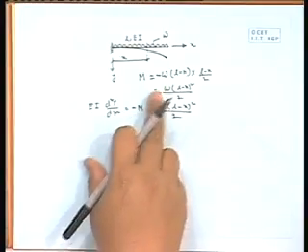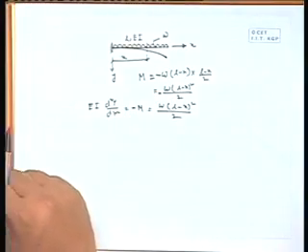So, minus minus will be plus, because we have taken sagging as positive, but here the moment is hogging. So, we have put minus, and if sagging is the positive moment, the expression will be with minus M. So, this minus minus will be plus.